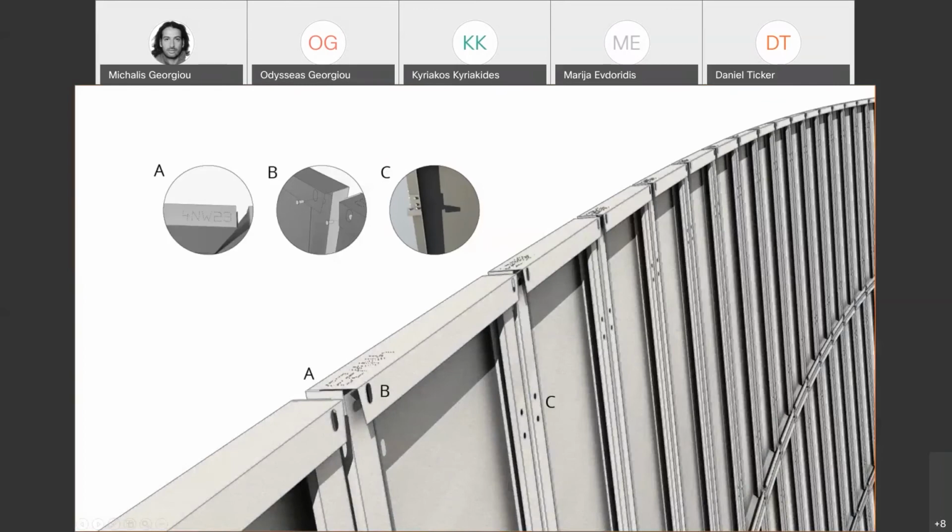Which meant that we had to build a bespoke system, a parametric model to correspond to this design. So panelize the whole building and input the surveying of the horizontal beams in order to cut the holes on the beams. This, of course, was adjusted many times, so each of the setting out of the floors was different, and each of the holes were placed on the exact locations of the setting out.